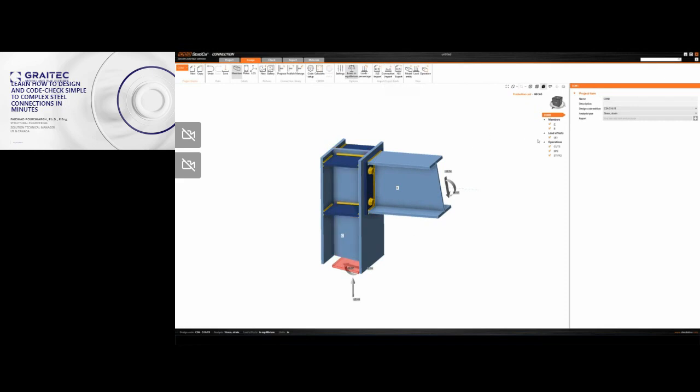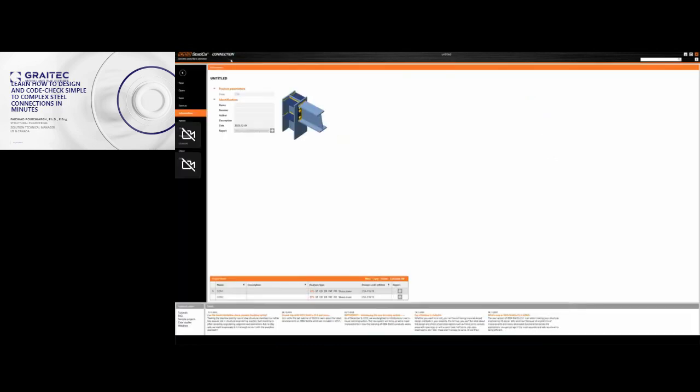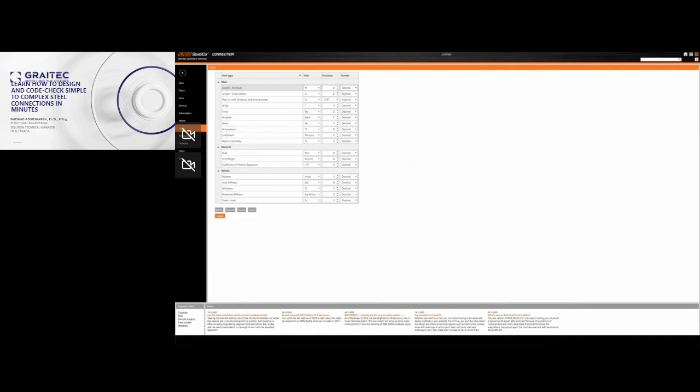Or here we have load effects, which is called LE1. I have just one right now on this template, which is called LE1. And using this table, you can go on and input your values. By the way, I am in imperial units now, but if you want to change it, you can simply go to units and change it to metric, as you see there, and click apply. So all will be applied. You can also go one by one and change them individually if you want.